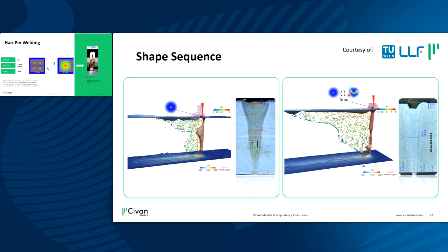And there are many strategies today of how to weld this part. What is common to all of them is that it's some kind of a wobble weld. That means that you take a single point and then you wobble it between the 2 hairpins in different motions. But what happens is that whenever you cross this gap between these 2 pins, it usually leads to spatter and porosity.